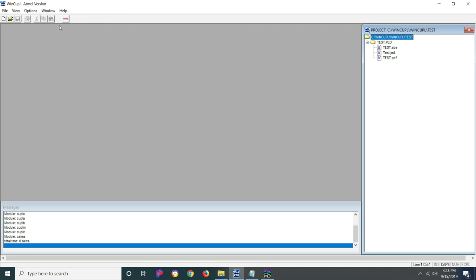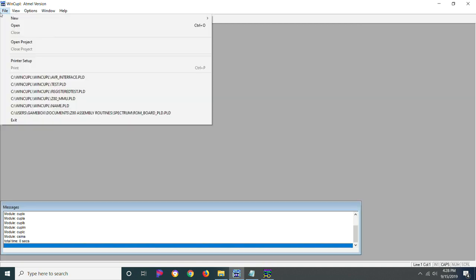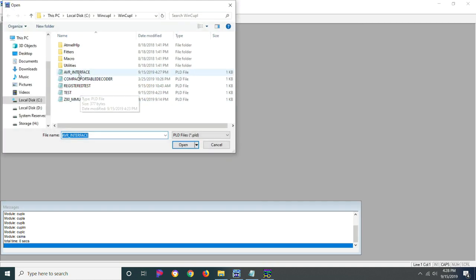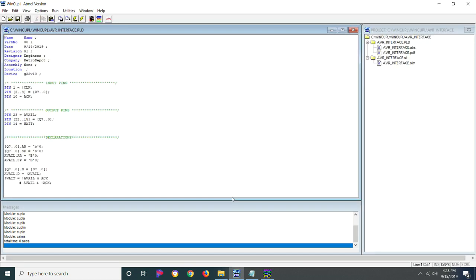Okay, so this is a good example of getting a little bit more complex. As you can see, we have a clock pin here. We have our data lines that are inputs, so D7 through D0. We have our acknowledge pin there, which is also an input in this particular AVR, and there's a reason for that in a minute, and I'll go over that. We have our avail pin, which is the pin that will be an output and read by the AVR, and we have our Q, 7 through 0, which is our data output, so it's latching that data onto the bus.